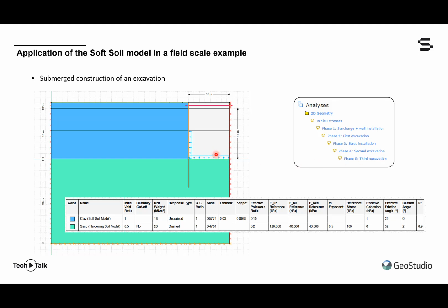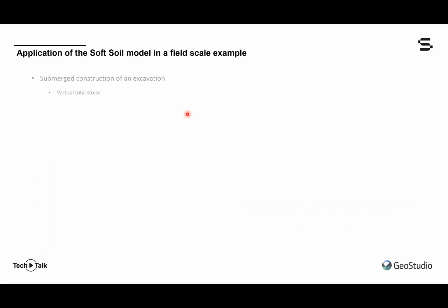And you maybe saw as the animation progressed that a hydrostatic boundary condition is being applied to the newly exposed ground surface after each subsequent excavation phase in order to put the water back. So in other words, Sigma by default removes all material, the total stresses from an excavation. And so we have to, since it is submerged in water, always at 2 meters below original ground, put that water back via a hydrostatic pressure boundary condition.